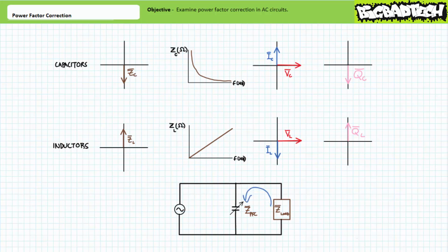At the opposite end of the cycle, the moment when the inductive magnetic field is collapsing and squeezing out current of a given magnitude, the power factor correcting capacitor is charging and sucking in this exact same amount of current. In this sense, the inductive portion of the load is dumping all of its stored power into the power factor correcting capacitor just when it needs to get rid of it.